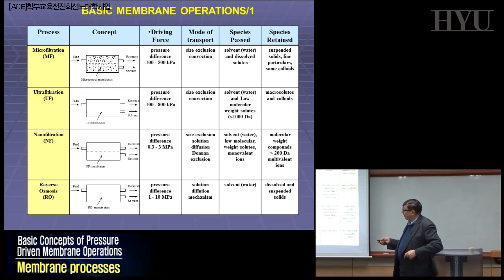But in principle, you must always have the concentration here and the concentration on the surface equal. So you can just predict what is going across your system with no problem from the initial value of the concentration. Not easy to realize this, because you have to control the concentration profile, but that's what we can try to have. Always cross flow, never dead flow on the membrane surface.